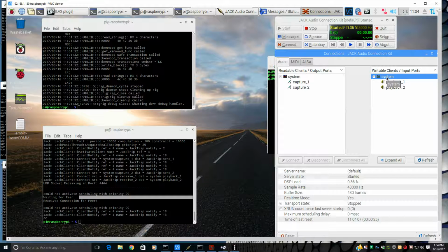We're sending the audio from a remote location over an audio streaming app called JackTrip, which we'll set up here in a second. And when it receives audio from that JackTrip connection, which will be a CW tone, that CW tone will come out of the speaker jack of the Pi, and with an audio cable it connects to the input of an audio-derived CW keying circuit, which just uses some diodes to rectify the audio voltage, and that keys the base of a transistor whose collector is connected to the CW jack, and it just grounds it. So that's how we send CW.